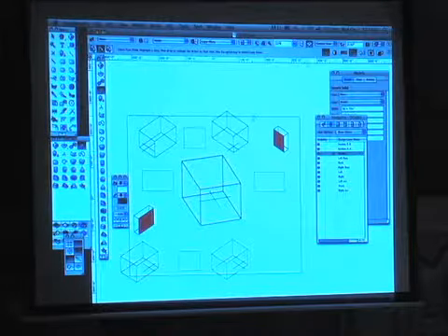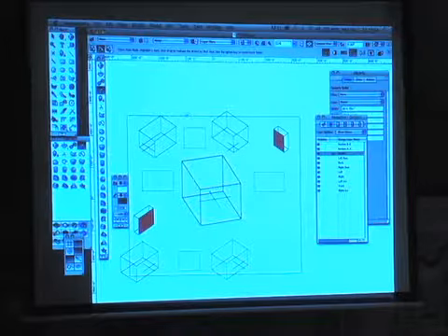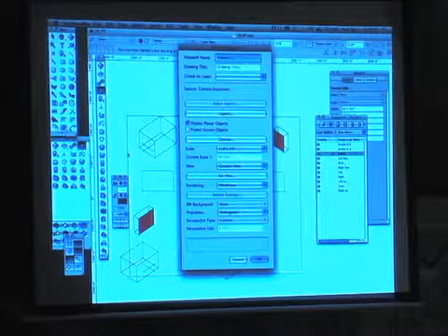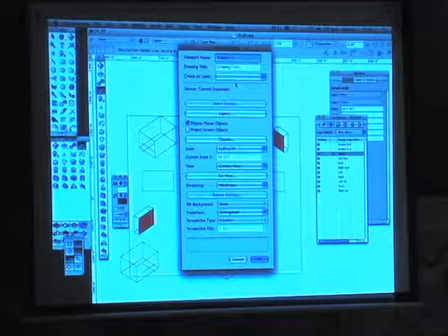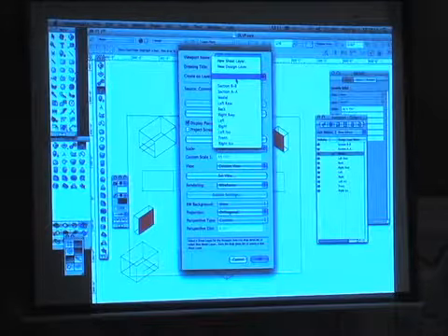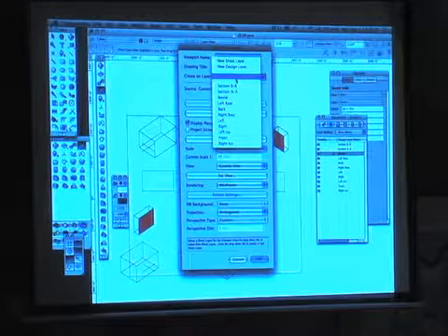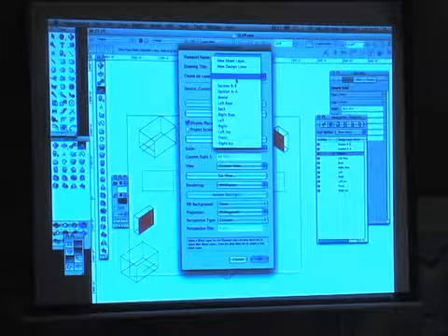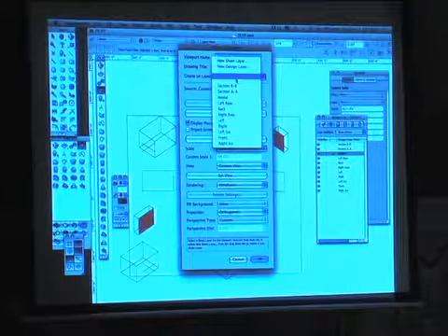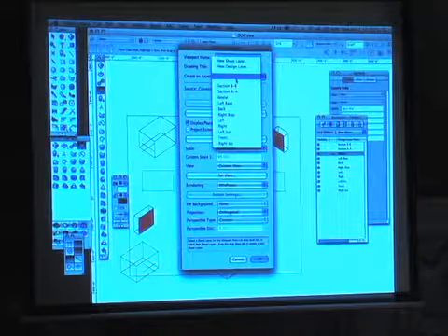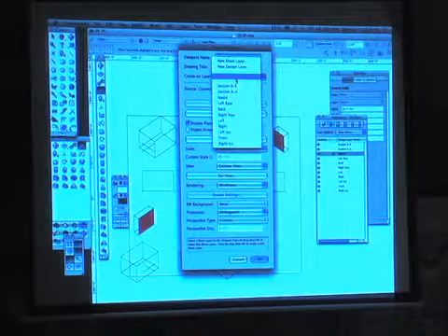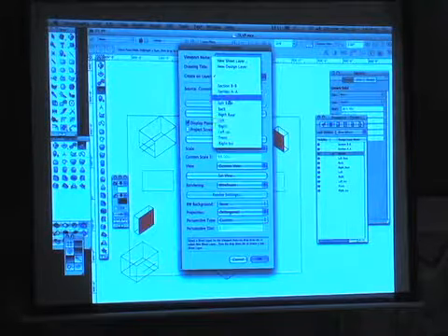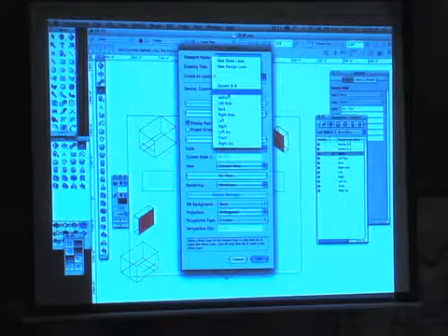The way I created it was, I created a viewport, give it a name, and what I found is you have to put it on a different layer for each one, because if you try and put them on the same layer, they're all going to take on the view that you set up. So if I want to see something from the left view and I put my right view on it, when I change that to left view, everything is going to be left view. So that's why I had to come in and set up a different layer for each one.